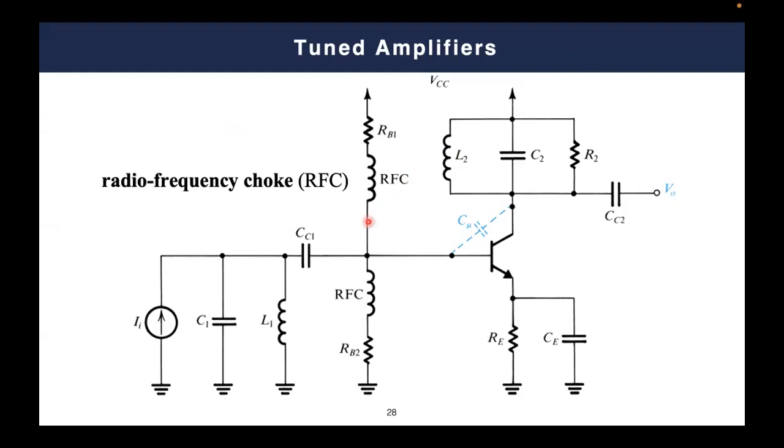Okay, so now we understand the role of these 2 inductors and the role of these 2 capacitors. What about this circuit and this circuit? Definitely, this one we already investigated: it is a circuit used in the tuning amplifier. So this is the source of a tuning amplifier, and this is where you have a 1 over LC resonance, in order to guarantee that your resonance frequency will be amplified with a factor called negative GMR, as we described together.